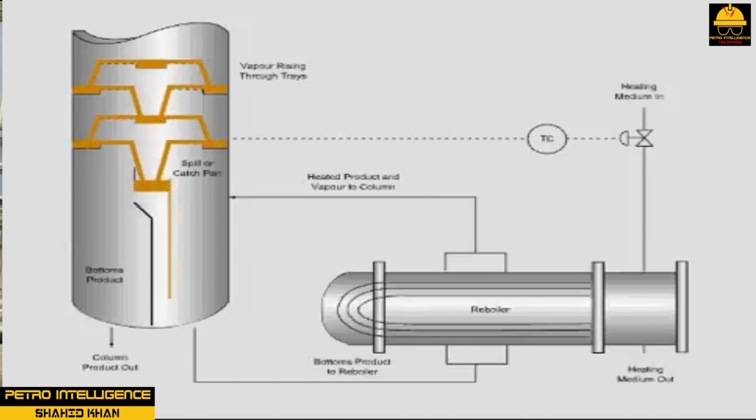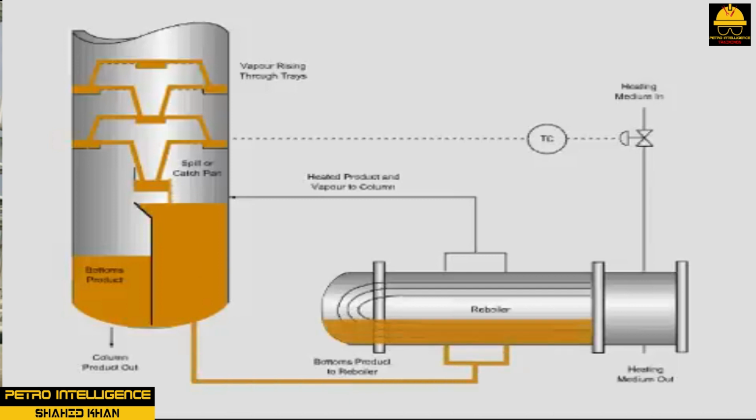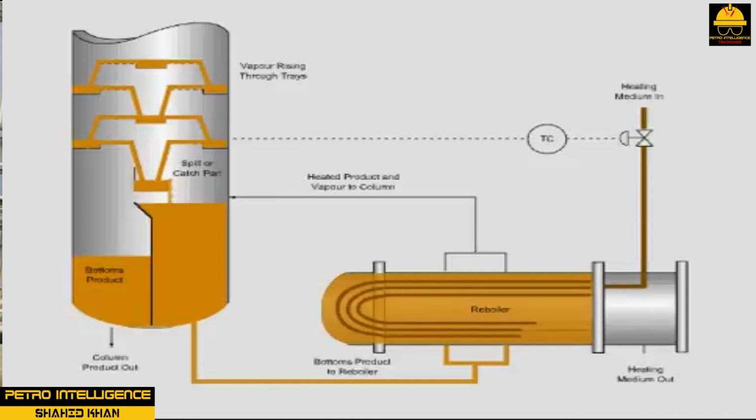When steam is used as the heated medium in a vertical exchanger, it enters from the top shell inlet and flows downward to the shell outlet to allow for the removal of condensate. The lower tube inlet of the exchanger usually takes suction at a point low enough on the column to provide a liquid level to the exchanger. A pump is not connected to the column and exchanger unless a forced circulation system is required.